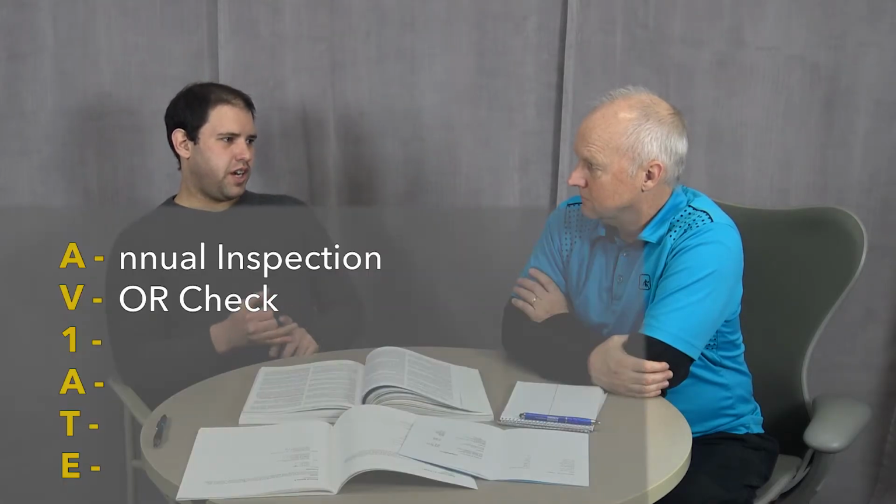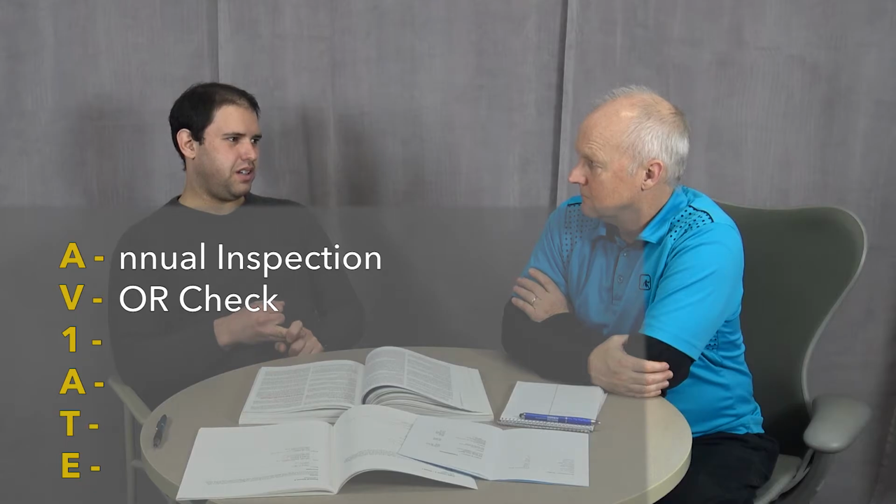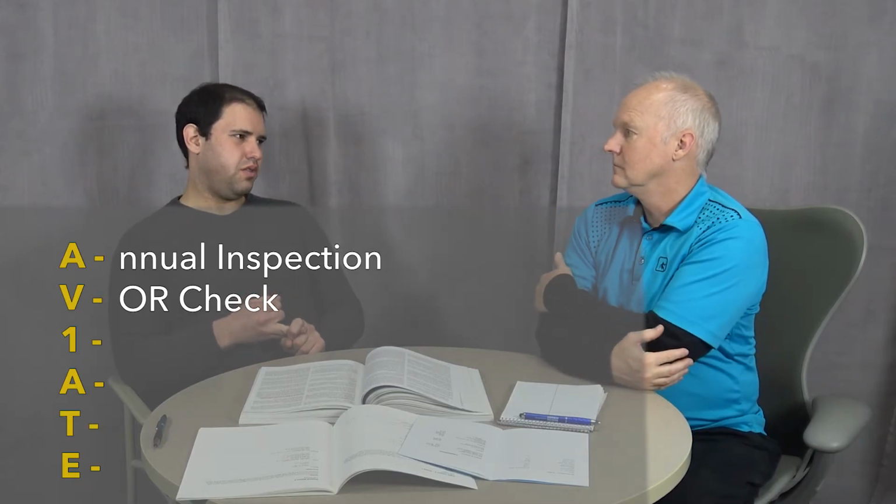The V in AVIATE is a VOR check. That's a check that can be done by a pilot. It's required if you're going to fly IFR, Instrument Flight Rules. So not required for visual flying, but every 28 days there are various different methods to verify that your navigation radio is receiving properly and is accurate. And you have to do that check every 28 days and make an entry in the logbook. So if you have a plane that's equipped with IFR, even if you're not flying, you've got to go out to the hangar and fire it up and check this and log it.